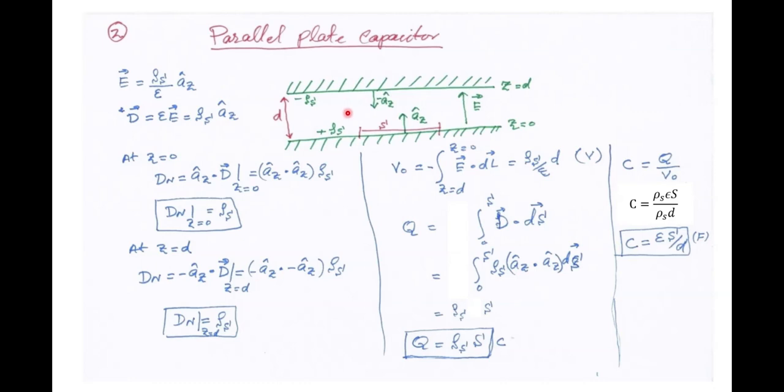So in order to define the capacitance of the parallel plate capacitor, we divide the conducting sheets located at z equal to 0 and z equal to d into incremental surfaces. We do this in order to avoid the non-linear effects which are produced at the edges of the parallel plates at the z equal to 0 plane and z equal to d plane.